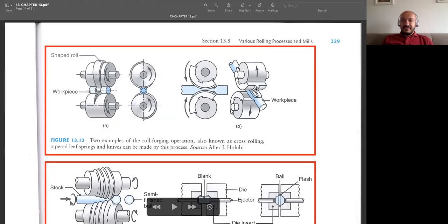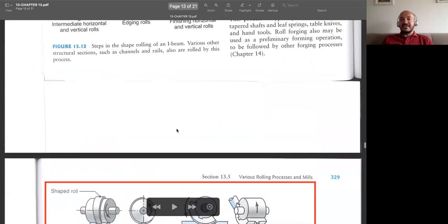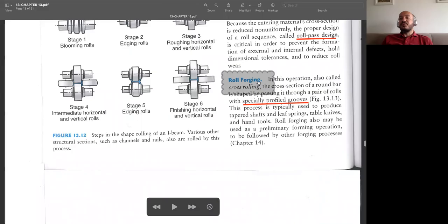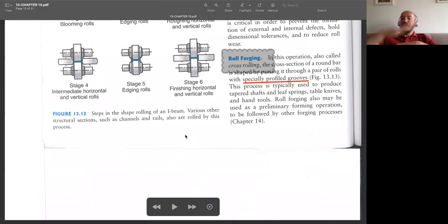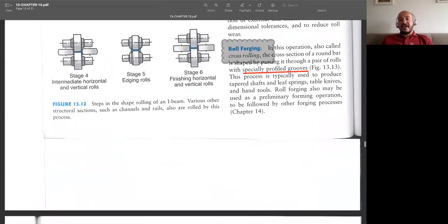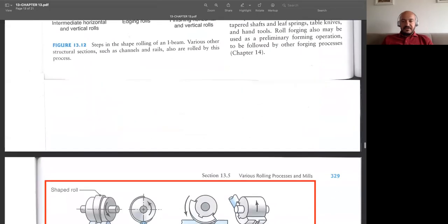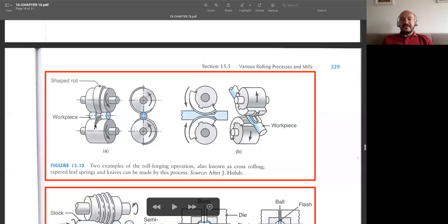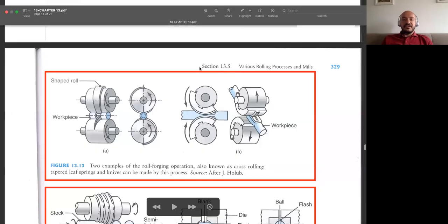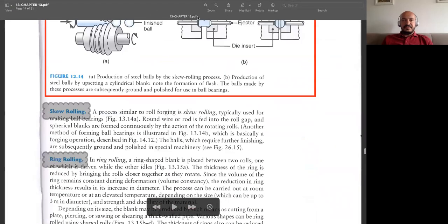You see, we have weird shapes here. So sometimes we have impact forces on the workpiece. That's why we have the term forging. We will discuss in the next chapter that in the forging process we have impact forces, and we apply them with the help of these discontinuities on the rolls.